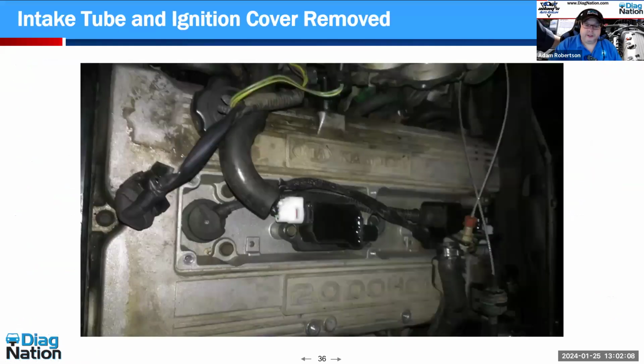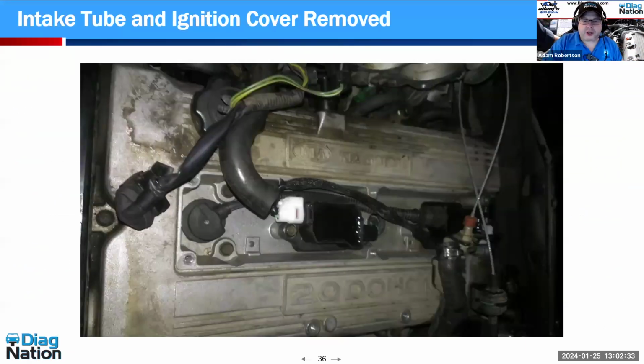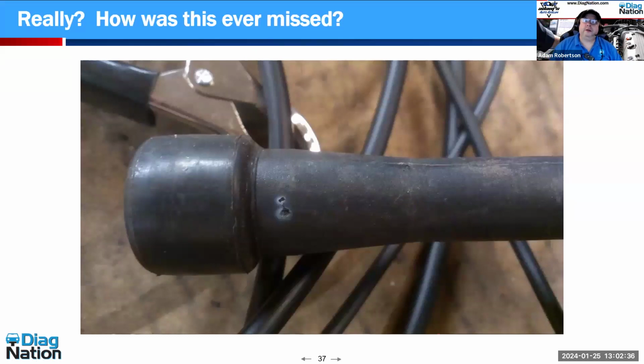Now, the problem with this car all along to look at the secondary was that you had to pull this off. But here's the clue, guys. Now that I pulled the intake off, I'm concentrated on going to one cylinder. Do I care about cylinder 1, 2, or 4? No. I proved that in all these waveforms. I got to go look closely at cylinder 3. Well, there's cylinder 3 for you. Do you see that? Oh, and I know some of you are going, oh, Adam, before you even think about that, I want you to seriously look at what this car did. That is a brand new plug wire.